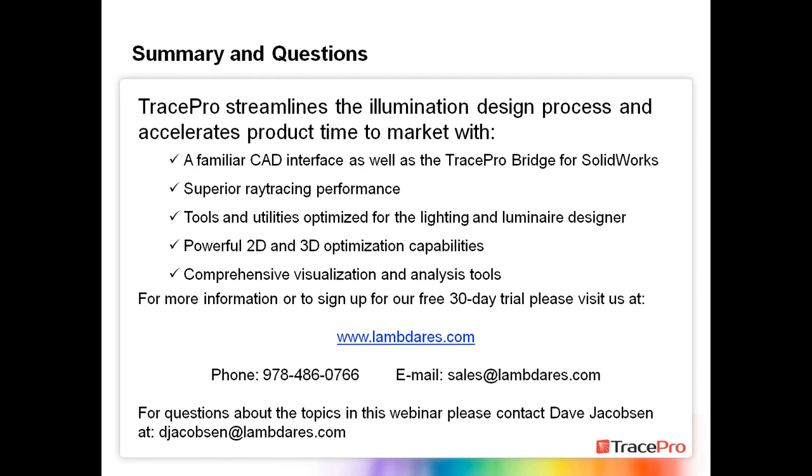Great. I see another question from the audience. In an optimization session, do you have a capability to export a CAD file? Well, what winds up happening is you export the file from the optimizer to TracePro, and then from TracePro you can save the file as an SAT file, or with optional translators, a STEP or an IGES file. So you can generate that 3D solid CAD file from TracePro. So you just send the geometry from the optimizer to TracePro.